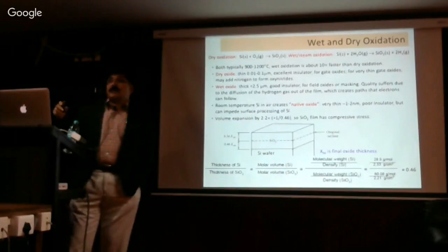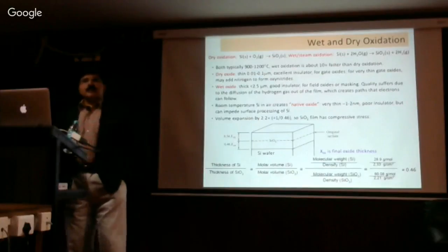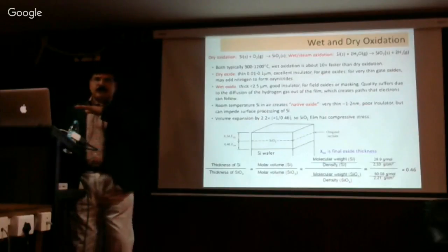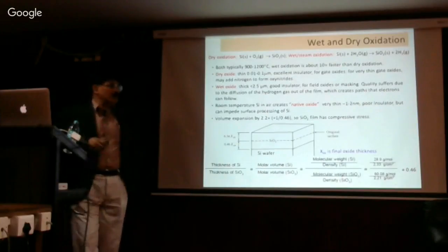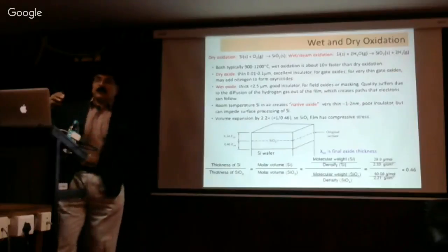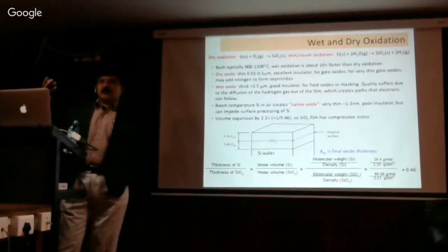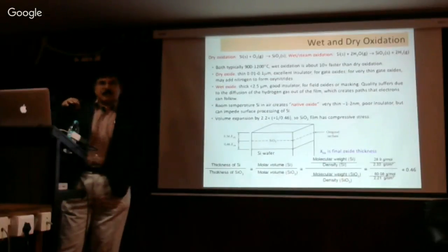So what people do is make sure that you have a good oxide to start with, so that it will block any further growth of oxide. And if you increase the temperature of the oxidation process, it increases. So people deposit high K materials on the top of the good quality thin oxide at low temperature, something like 200 to 250.